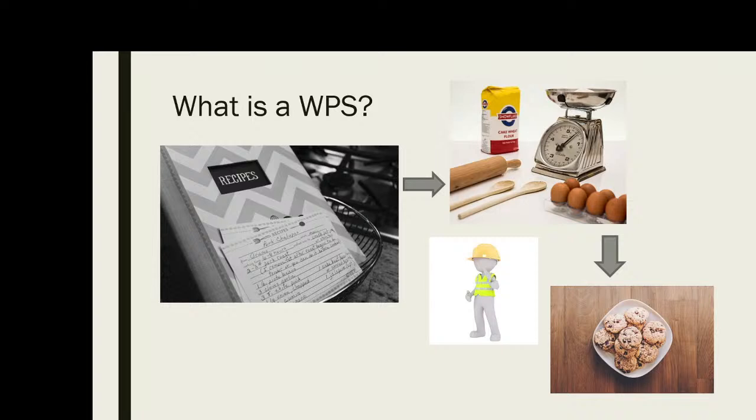So a WPS is just a recipe card. It's just telling us what goes into the chocolate chip cookies. Each chocolate chip cookie gets this, or each weld gets this, and this much post-weld heat treat. That's what a WPS is. And a PQR supports a WPS. So as I'm going through this, I'm kind of talking, because there's two things when we review these documents.